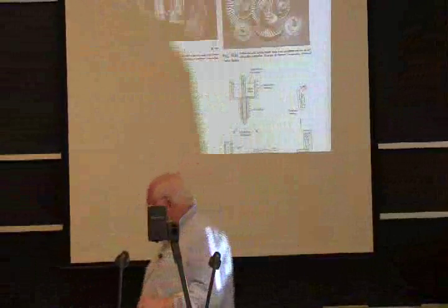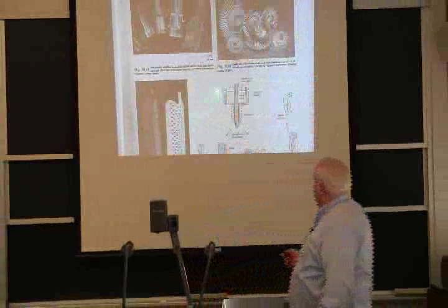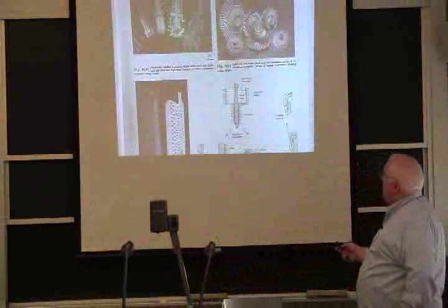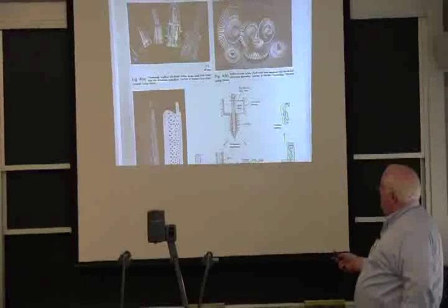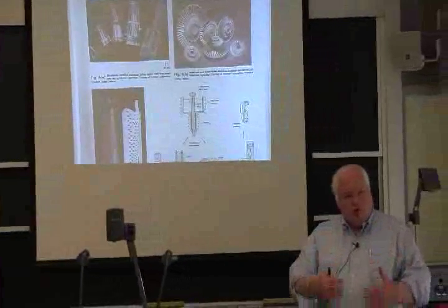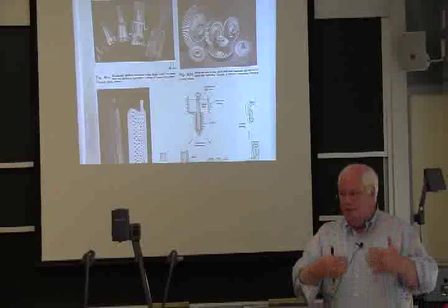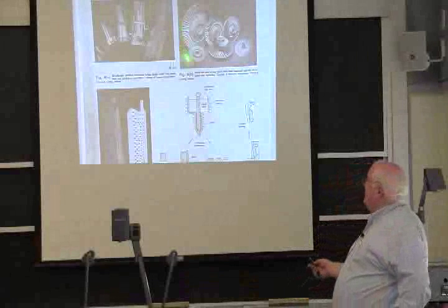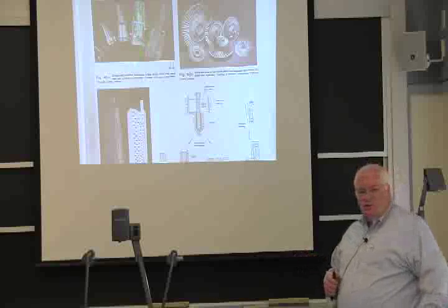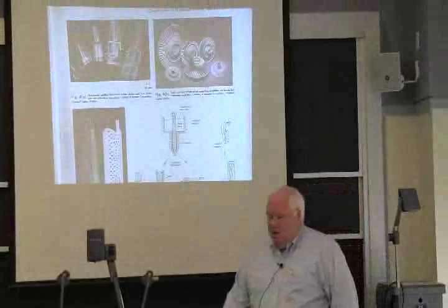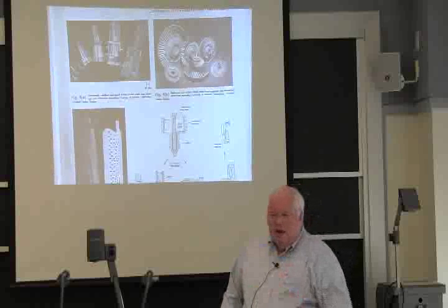Well, in the 1950s, the standard turbine blade was just a casting, like a lost wax casting, like my brass rat, multigrain. But by the 1960s, people were learning to cool it directionally, like using a chill block, cooling it in a gradient furnace where you have a temperature differential and pulling it through slowly. By the late 60s, people were learning to make single crystals. By the 70s, we had that kind of technology. That blade's probably about a 1980 technology blade.